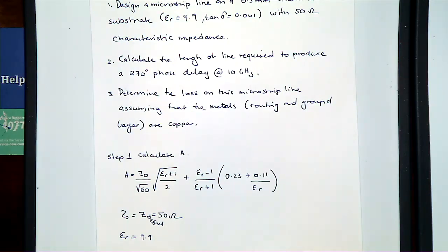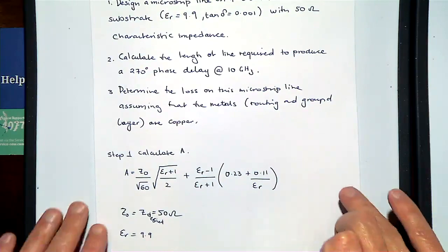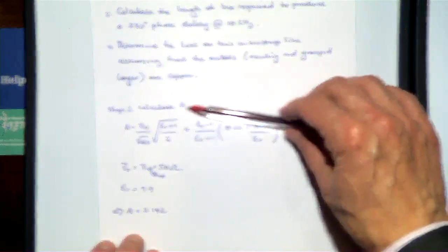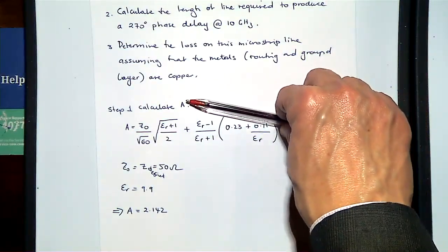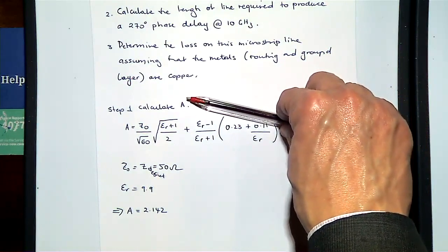Or as your colleague has just pointed out, if you want 90 degrees out of phase. For example, if you were designing your communication systems and you want your sine and your cosine, you put your sine in one line, and you put a sufficient length of line so you get a 90 degrees phase shift on the other end.